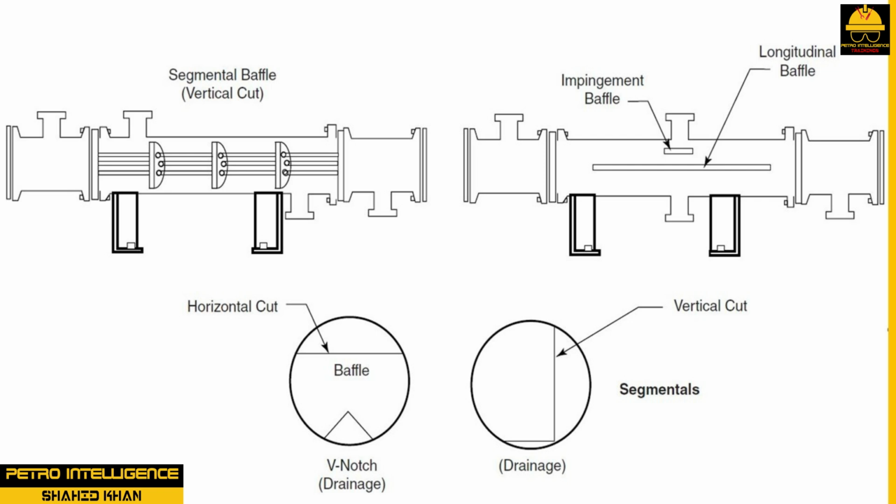The choice of which arrangement to use is based on the required service. For example, a vertical arrangement is typically used in horizontal exchangers used as condensers, reboilers, or vaporizers. Systems transferring large quantities of suspended solids may also use this design. The vertical design allows liquid and solids to flow around baffles.